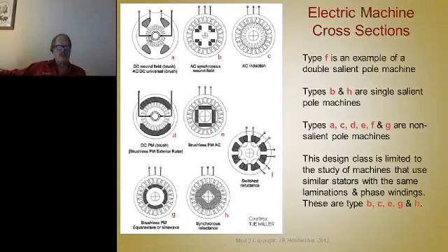So as this rotor rotates, when the current is applied into those coils, it causes the polarity of those coils to be such that they move. That will put that torque component on the conductor, which pushes against the steel teeth of the rotor and causes it to rotate.